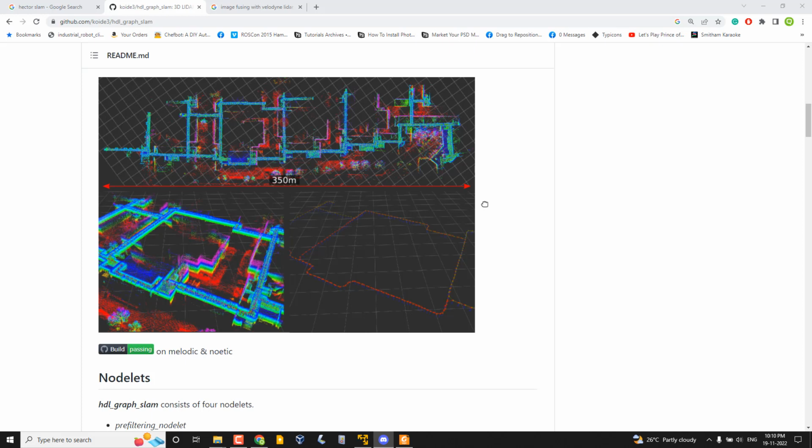So that we have seen in the mapping. The SLAM algorithm can do the mapping and localization. Okay, so the map to ODOM actually shows where the ODOM frame is with respect to the map, or where the robot is with respect to the map. Okay, which is also shown when we localize. So this frame map to ODOM will also be published when we do the localization.